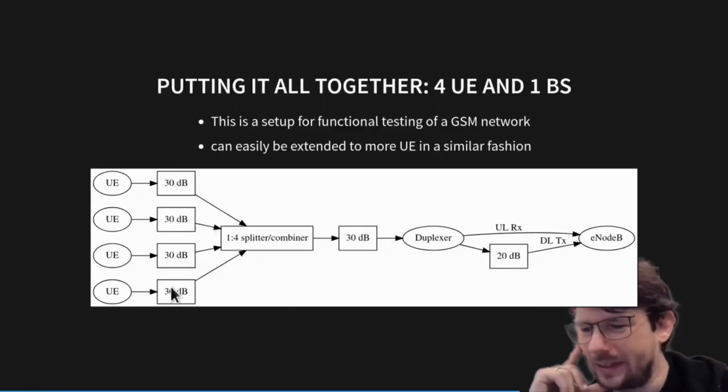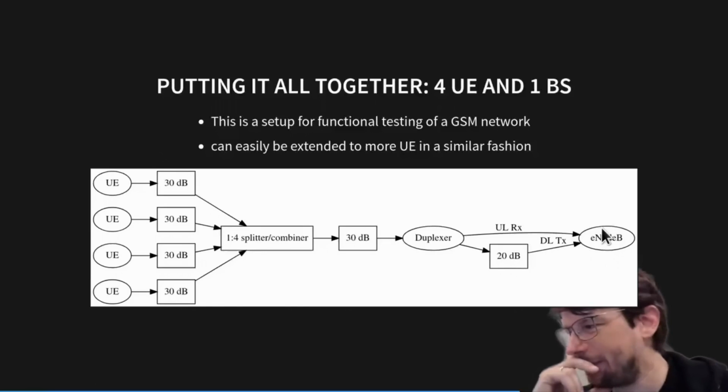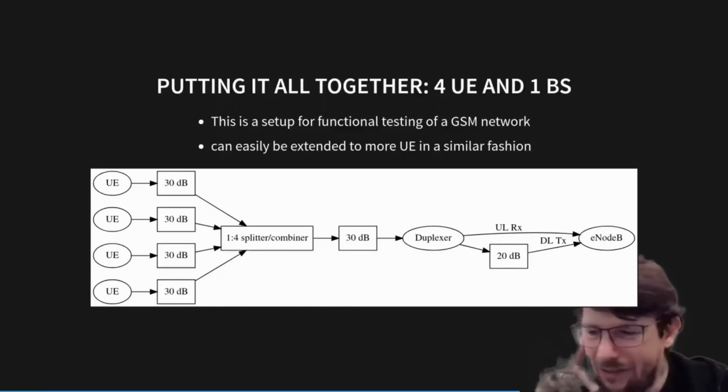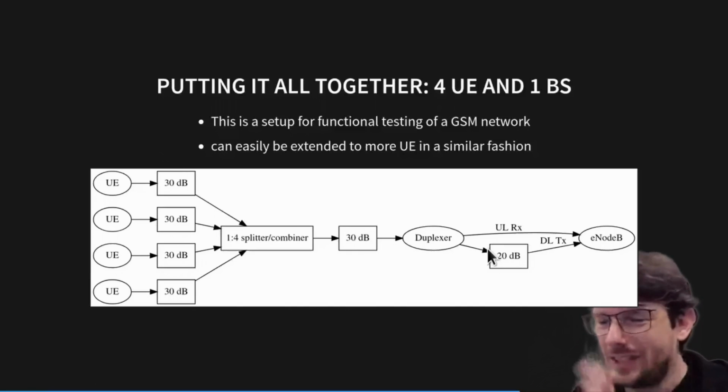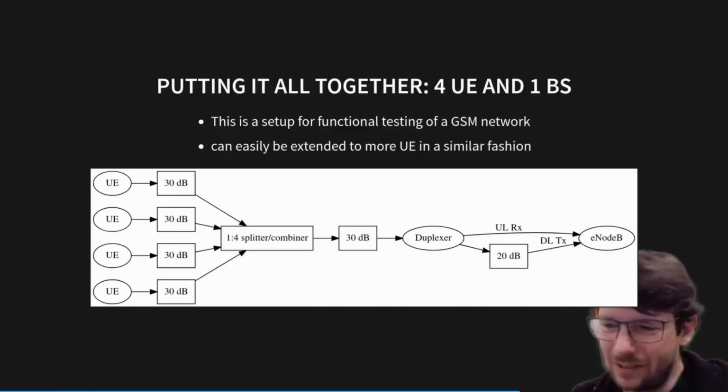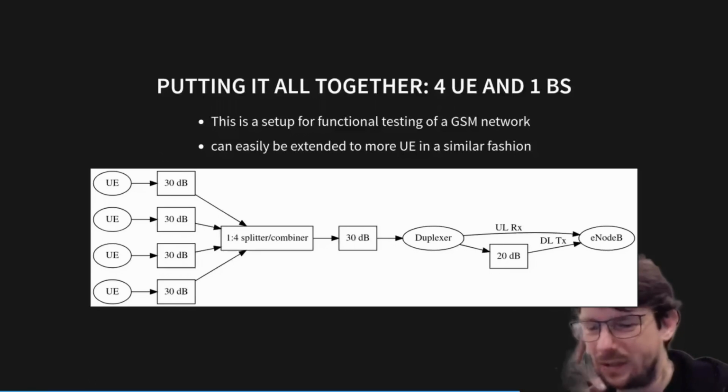On the user equipment side, it's typically not a concern, but here, this 20 dB attenuator, if this really is an eNodeB that can transmit at, whatever, let's say, even only 10 watts or 20 watts, you need a rather high-end, beefy attenuator that has a large heat sink, so it can actually handle that RF power that it is exposed to here. And that's really all that is to it, to designing such an RF distribution network and putting it together.